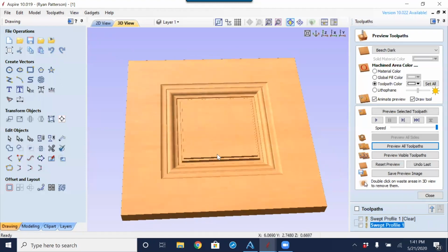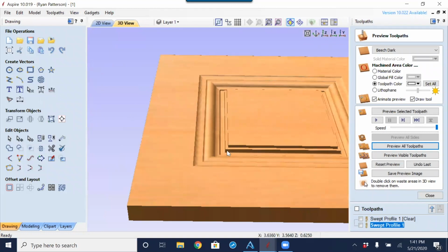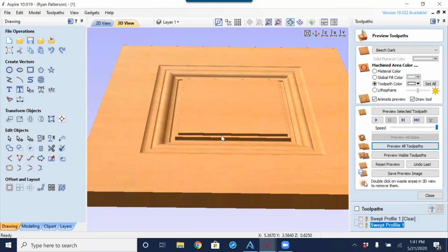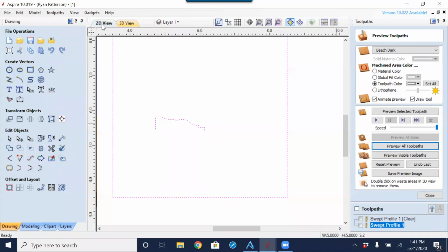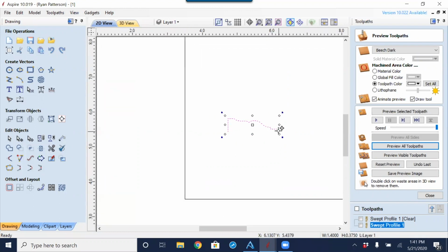All right, so that is the basic shape and the profile that we have selected. It comes around and comes down into there. So now if I wanted to create a frame that we're going to put some text or V-carving or a 3D model or an image in the center here, we really should remove that area, do an area clearance or a pocketing toolpath around the outside, or really the inside of this, because again, I'm just going to drag this over to show what we have.